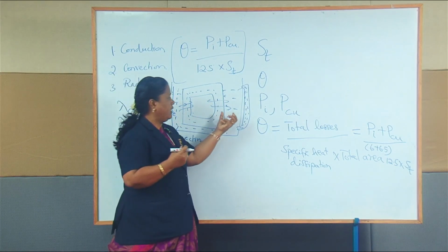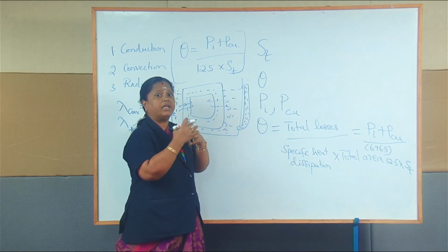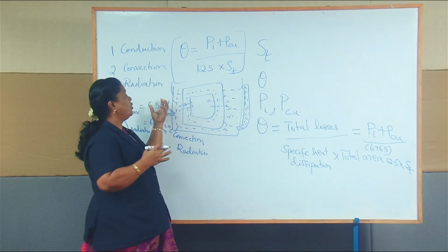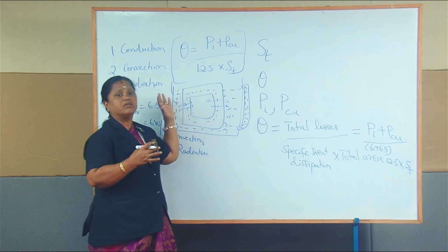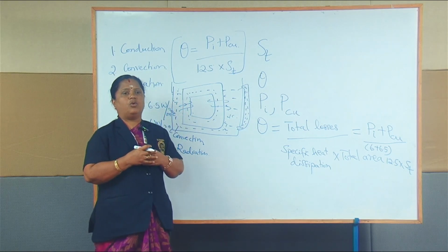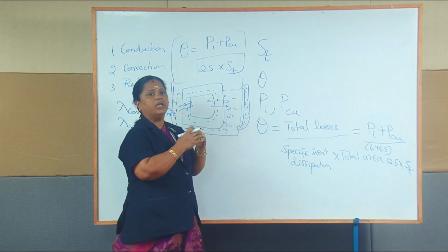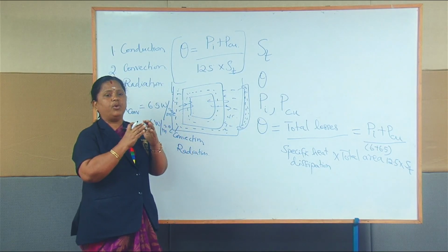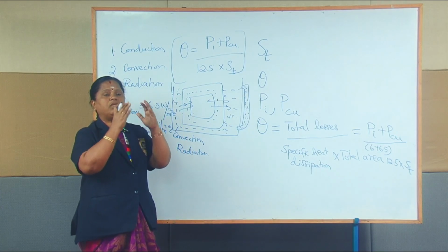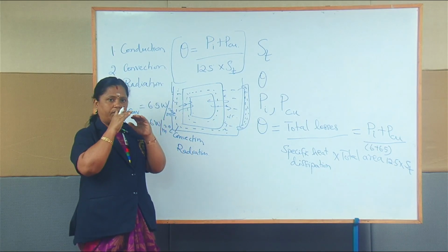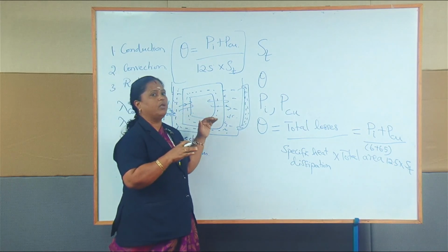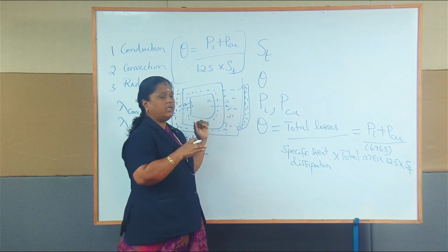So, the volume of the oil will increase if more cooling tubes are placed on the surface of the tank. So, if cooling tubes are placed, how the temperature rise relates, and how the temperature rise is maintained or reduced with the help of cooling tubes, we are going to see in the next section.